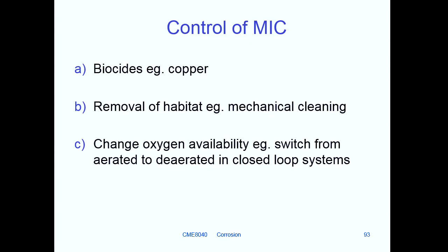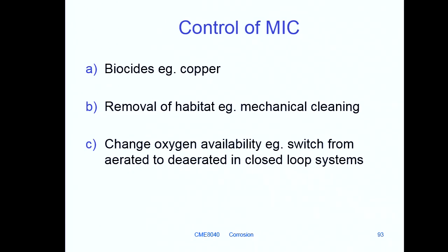The tubercles, these little igloos with this symbiotic relationship of the aerobic and anaerobic bacteria, you can, of course, mechanically clean the surface and remove them, or remove the whole film if it's become a solid film, and that slows the process down, evens out the corrosion, if you like, because it's under the tubercles that you're getting this localized pitting attack.